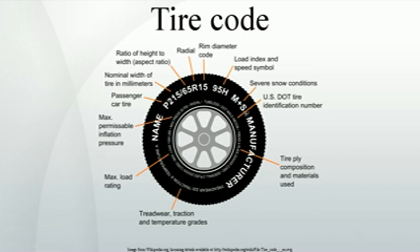Tires with a speed rating higher than 186 miles per hour, 300 kilometers per hour, are indicated by a Y in parentheses. The load rating is often included within the parentheses, for example, 86Y. In many countries, the law requires that tires must be specified, and fitted, to exceed the maximum speed of the vehicle they are mounted on, with regards to their speed rating code, except for temporary use spare tires.